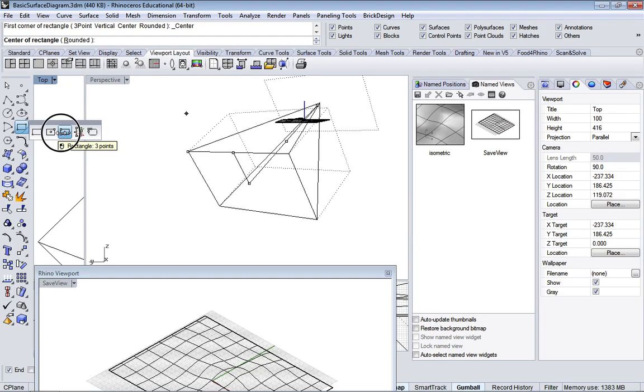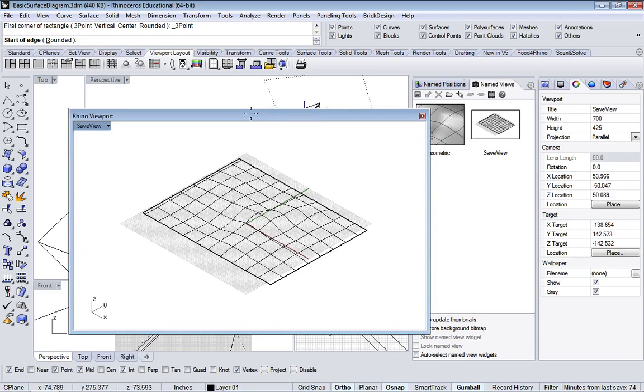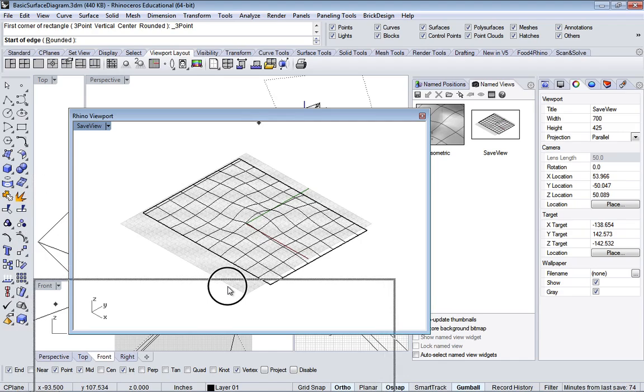So what we want to do is say, give it 3 points so it will build outside of the construction plane at the angle of the camera. So we're going to click that one. We're going to select, make sure that down at the bottom that your object snaps. This was turned on, so it's highlighted. And then make sure that point is selected. Otherwise, you won't be able to select these things and you'll find frustration.